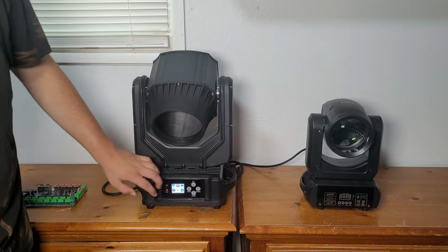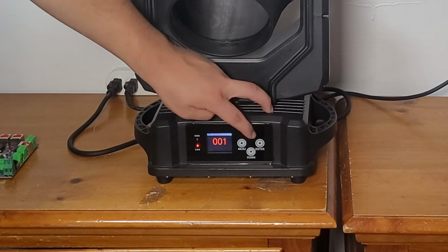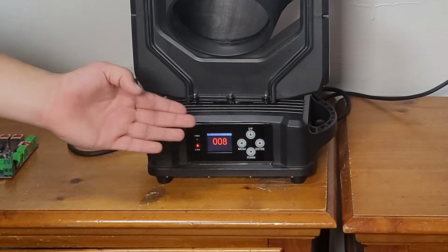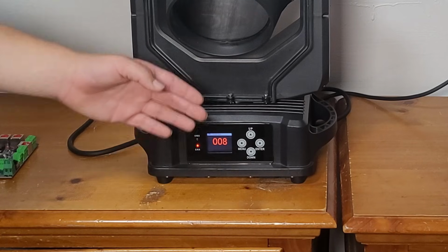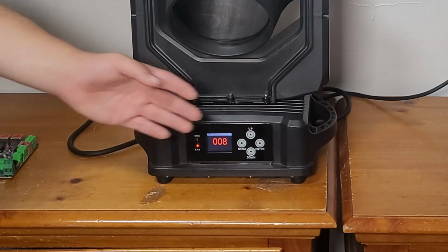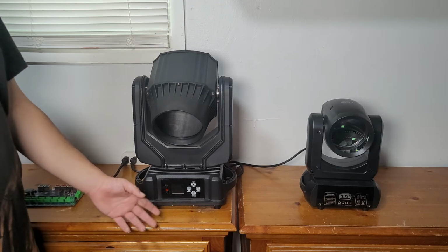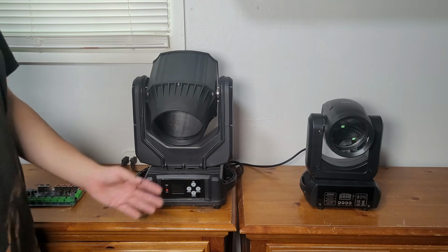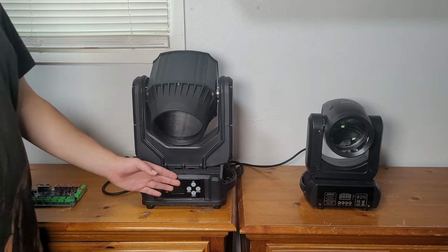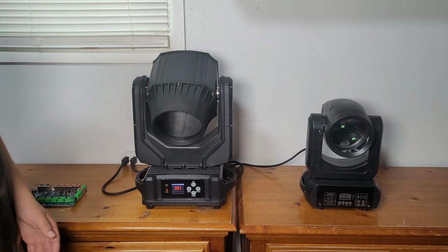But as you can see, I can go to the menu and hit the address setting to change what the start address is, or the DMX address. So I could set it to, let's say, 8, and now this means it will start reading channel 8 and the next 14 channels after that, because it needs 14 channels of data. This number can go all the way up to 512, since you could fit 512 channels in a universe, but it wouldn't be able to read anything beyond 512, since that's the highest you can go. I'm going to leave it set, though, for 1, since it's the first one in the chain.